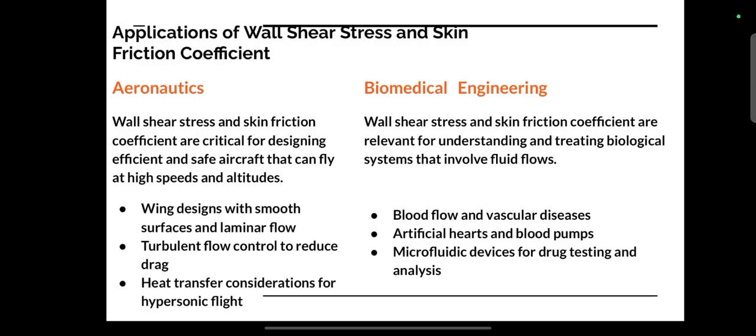Application of wall shear stress and skin friction coefficient. We have used this in multiple industries like aeronautics and biomedical engineering. The first one is aeronautics. Wall shear stress and skin friction coefficient are critical for designing efficient and safe aircraft that can fly at high speeds and altitude. Wing design with smooth surface and laminar flow, turbulent flow control to reduce drag,